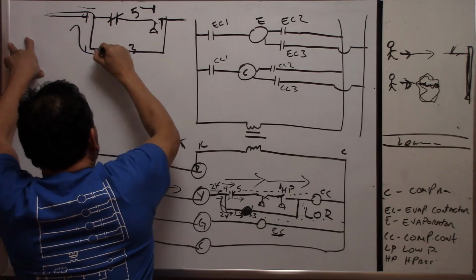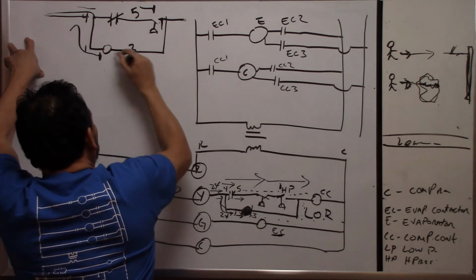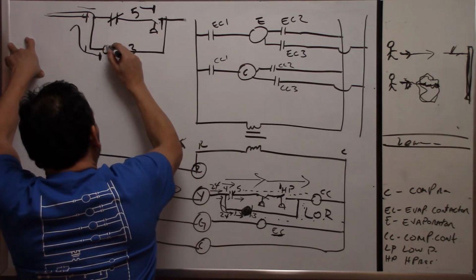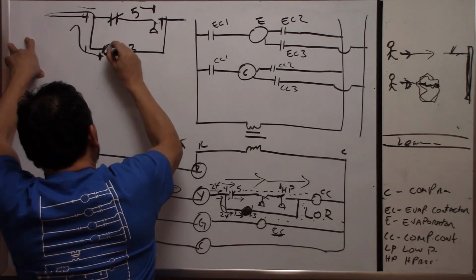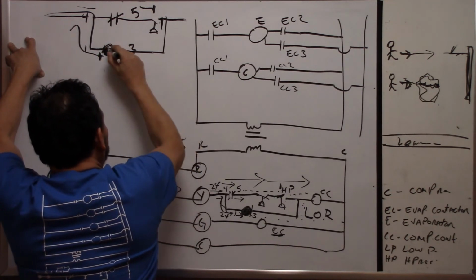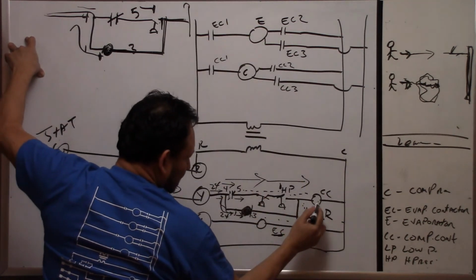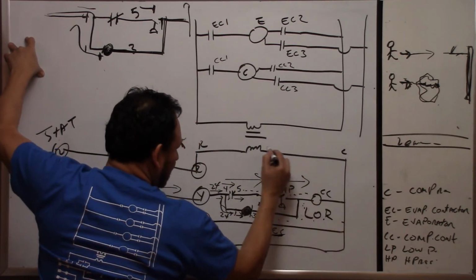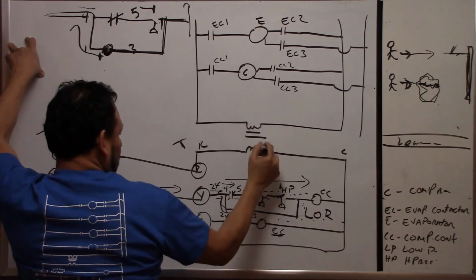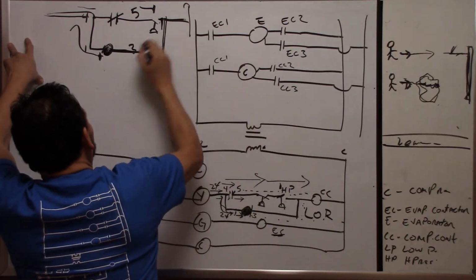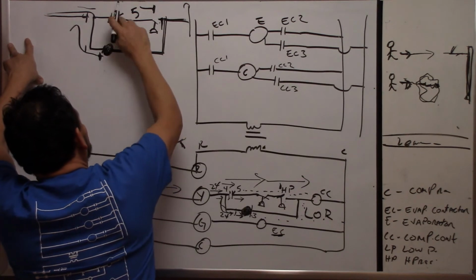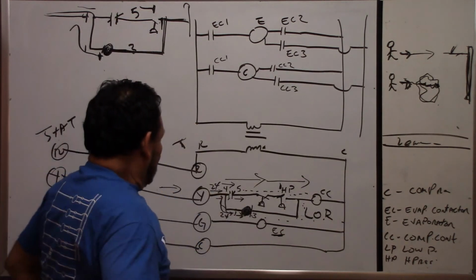And since you have voltage hanging over here and waiting, because all of this was 24 volts, this coil gets energized. This goes to common, because remember, this here goes to common, and right here, common. So this goes to the transformer. So this energizes, opens this up.